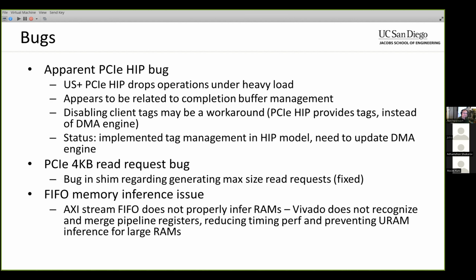What we saw is that at certain load on the Intel side, we see that the DMA engine at some time responds to a descriptor fetch request with empty, and then this DMA operation is dropped as well. So basically the packet is lost. Okay, well, this doesn't cause a lost packet. This causes the entire data path to hang. Oh, okay. Yeah, that's a different thing. Yeah. This is a much more serious problem.